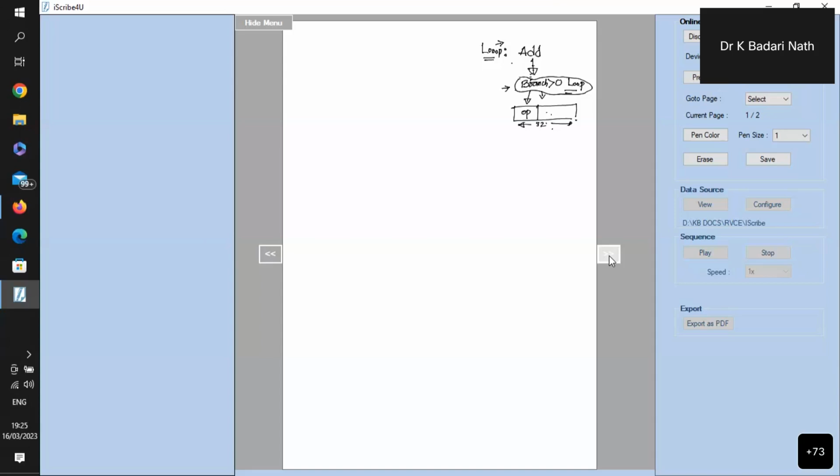In the sense, if I am able to refer to this loop in the complete memory, see, if this is the memory, starting from 0, let's say it goes up to 1 GB minus 1. So if you are referring to the label loop, the address of this is 32 bits, because why? I am referring to it with reference to what? From 0 to 1 GB.